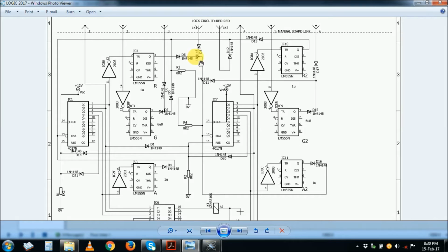And make sure where the diodes are connected, you never leave inputs for logic gates or combinational logic systems open ended. You must tie inputs to a certain potential, because the diodes are directional. You must make sure that you put a resistor like what I have done here, so that the clocking input is actually wired to 0 ground through a resistor. And this resistor wired to ground is actually for pin number 13 of IC1.